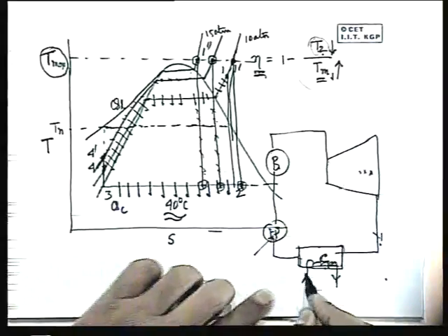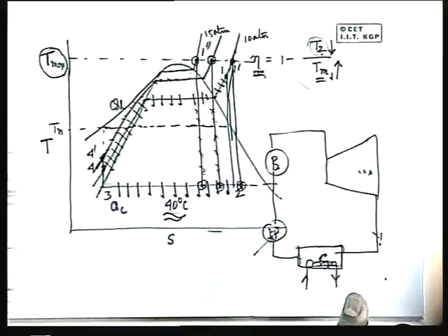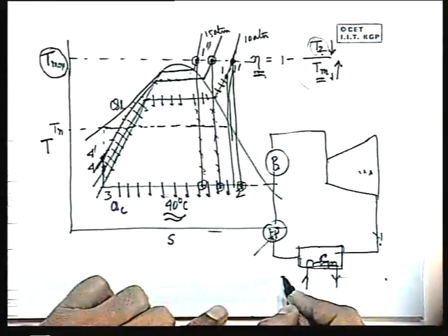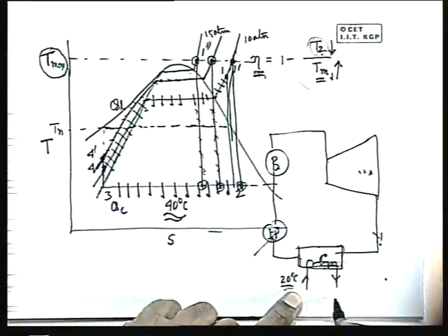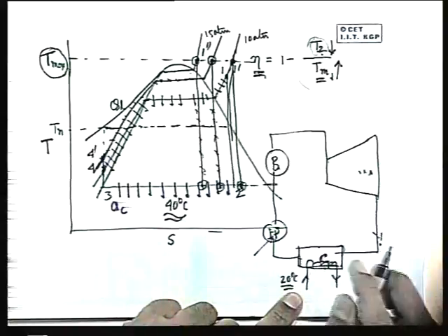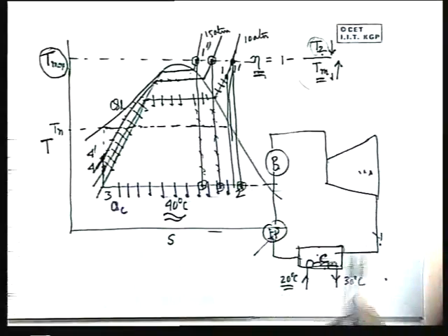What is that? Now you know, for cooling this is very important. I am telling you, I will ask this question in an interview when you may face me. The cooling water which is being circulated within the condenser is taken from the atmosphere, so it has the temperature which equals the ambient temperature. Let this temperature be 20 degrees Celsius. Usually there is a rise in temperature in a condenser in a power plant by 10 degrees or so. Let this come to 30 degrees Celsius. Now we will have to consider that the steam which is being condensed must be at a temperature a little higher than these two temperatures. That means a little higher than 30 degrees Celsius, otherwise heat will not flow. That means steam has to condense.